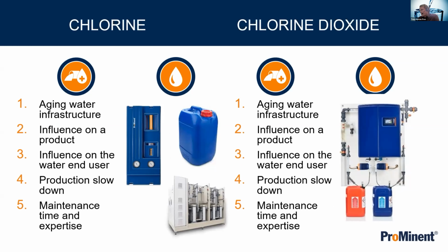That's where we move to our chemical disinfectants. The main advantage of these is they have a residual ranging from several hours to several days. They can resolve issues for aging water infrastructure because they have that residual. Chlorine is good at preventing biofilm. We've just seen several biofilm issues for your RO production. Chlorine dioxide is actually very effective against biofilm and actively removes biofilm in pipework.